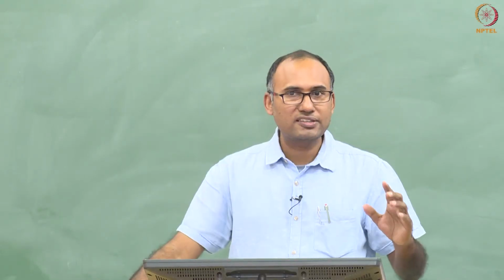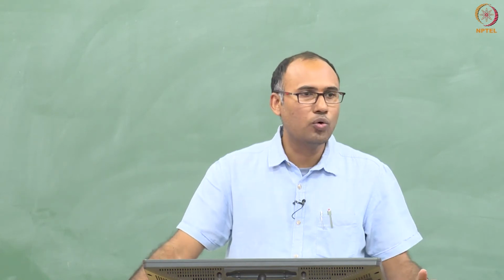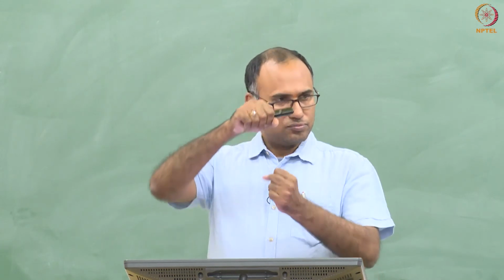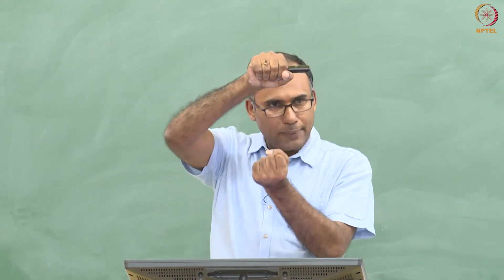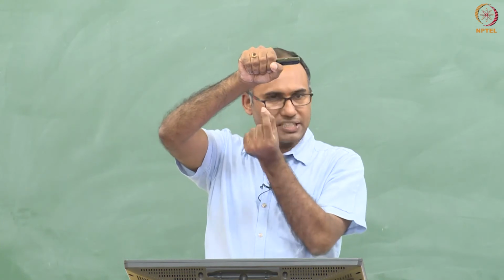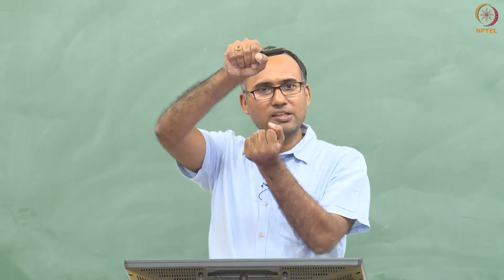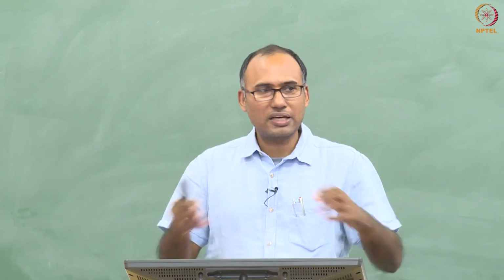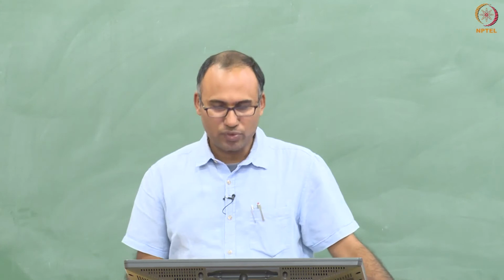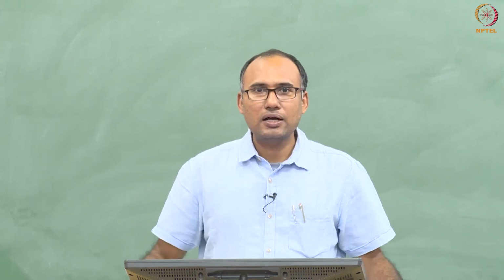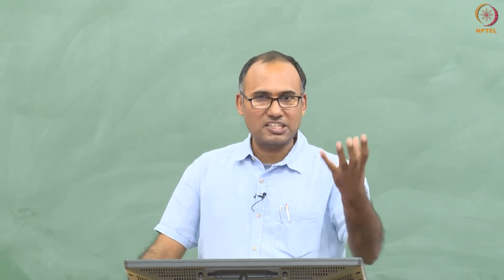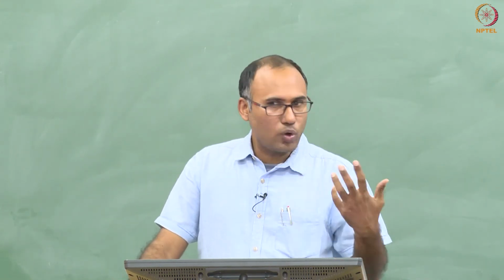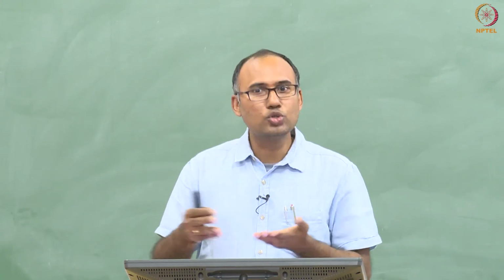In the last class we looked at the Griffith's analysis. If you take a member, apply a load, hold it with the grips and then insert a slit, and as you continue to increase the length of the slit, at a particular length the crack propagates suddenly. Then we looked at the reason for creation of the surface: the strain energy present in the material is released, and that is what is responsible for creation of the two new surfaces.